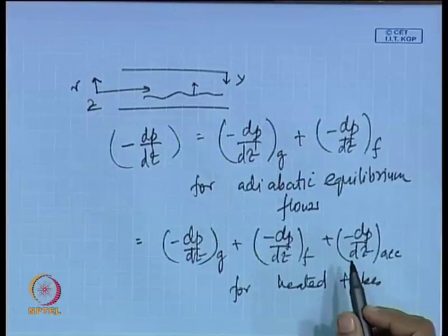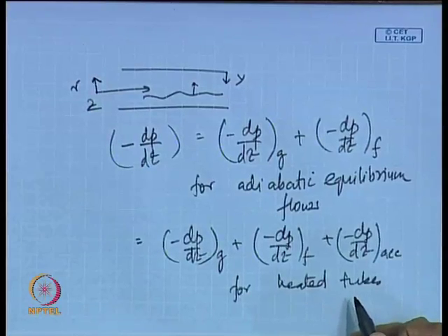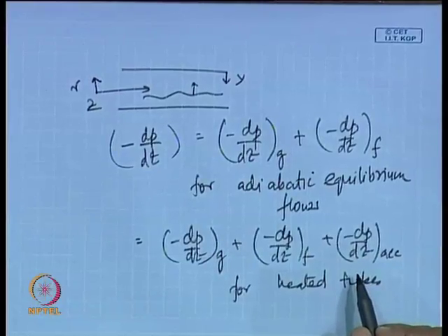Under that circumstance, either the liquid goes into the vapor phase or the vapor comes to the liquid phase. Naturally, some portion of one of the phases is either accelerated or decelerated. So, for such situations we have the acceleration pressure gradient. But whenever we have heated tubes accompanied by phase changes, it is no longer a single phase flow situation, isn't it?